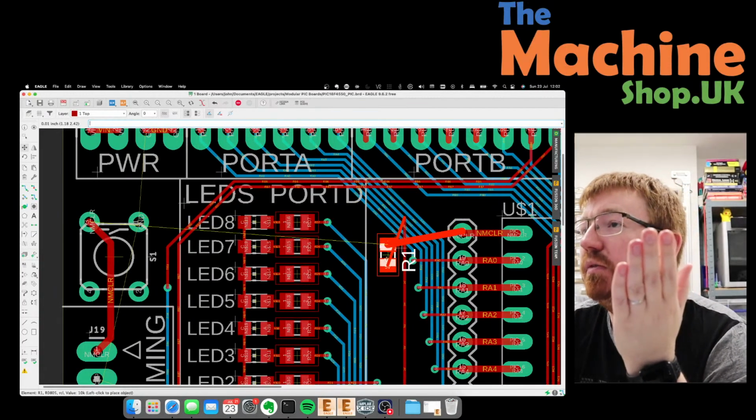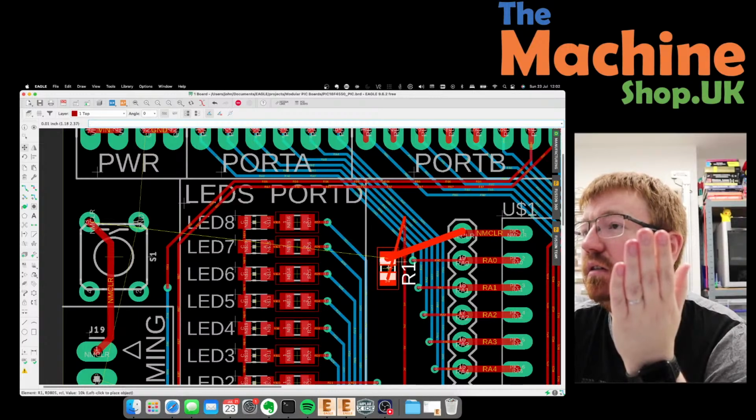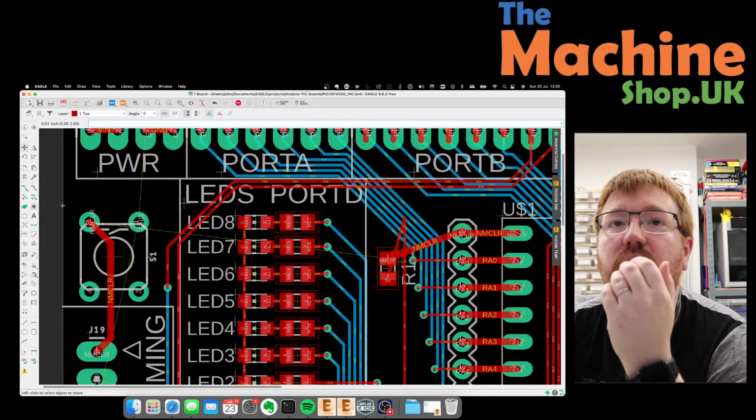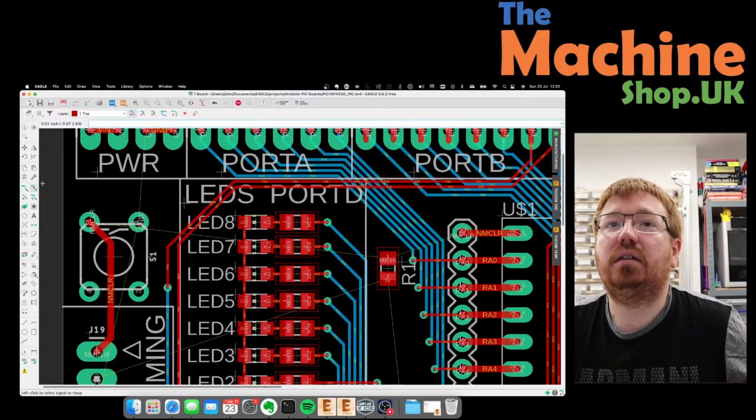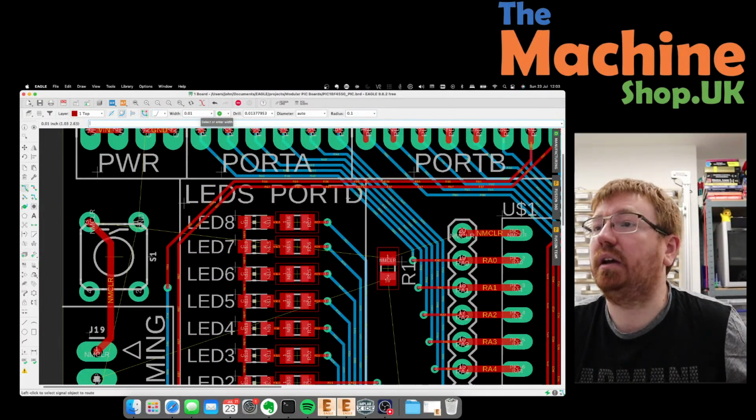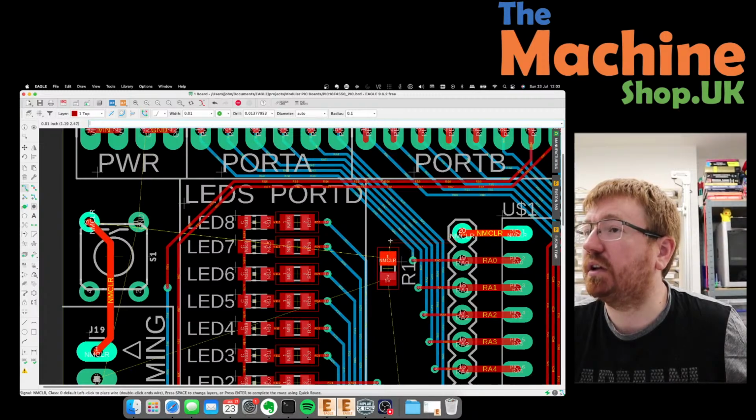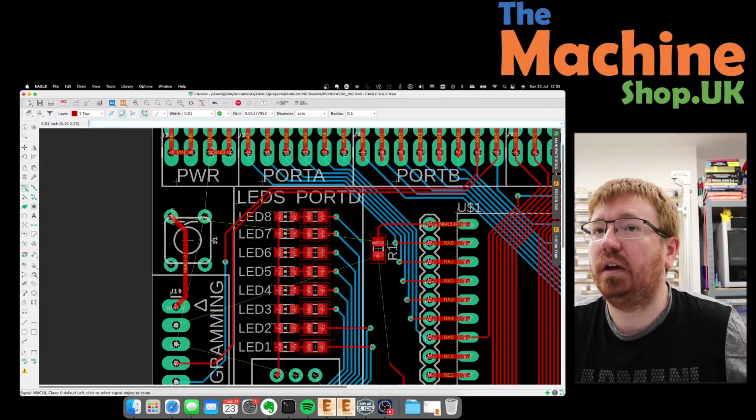Oh, actually, if I move that out to here, let's get rid of those ugly tracks. Nope, that one, and that one that I've just done. And then I can top layer. Yeah, it doesn't need to be a big fat one for master clear. There we go. Then this master clear can...